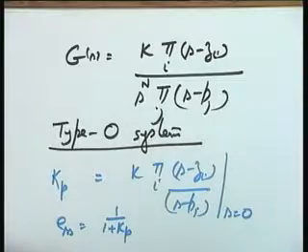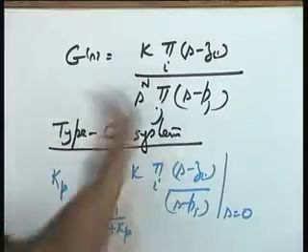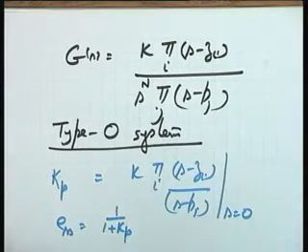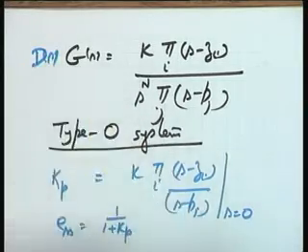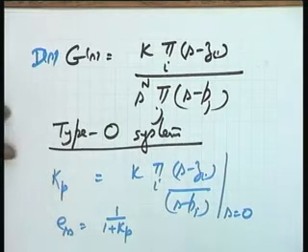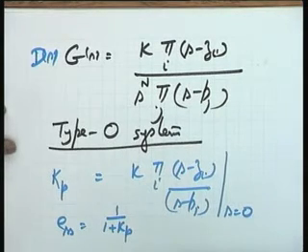Okay. How about the steady state error to ramp input, that is, what is kV? Let me not write it, you can keep on answering quickly. What is kV in this case please? A type 0 system, I want you to give me the value of kV. I am sorry, take it DsGs total including the controller. Is kV 0? Is the answer given by him correct?